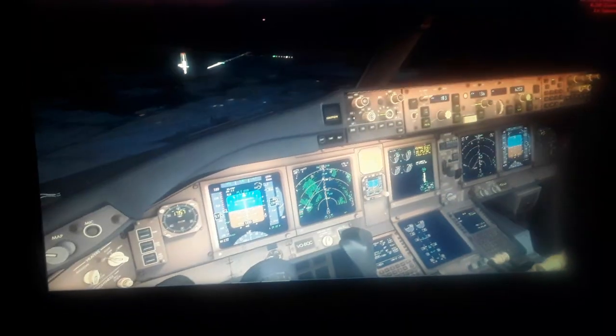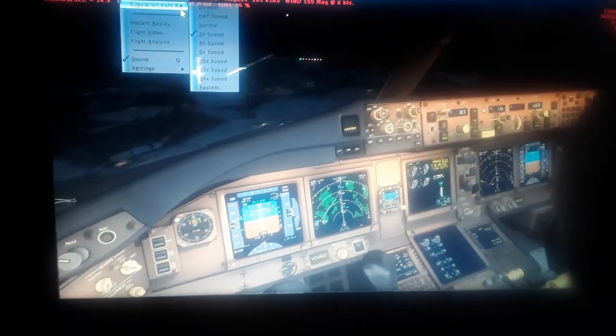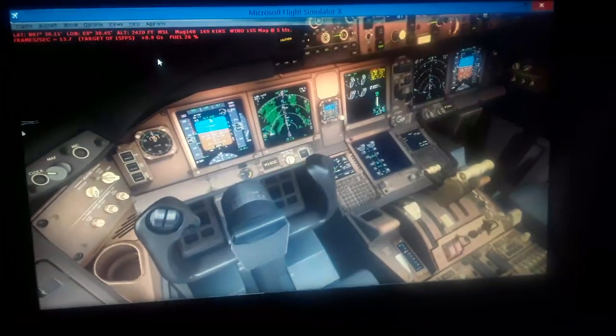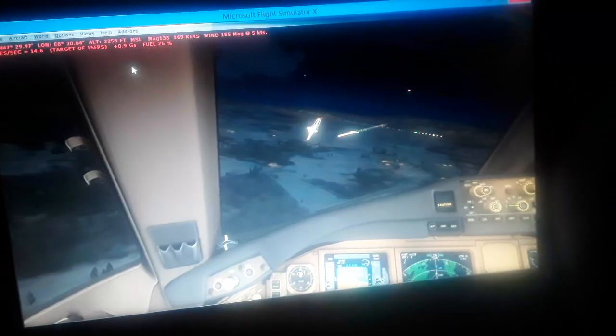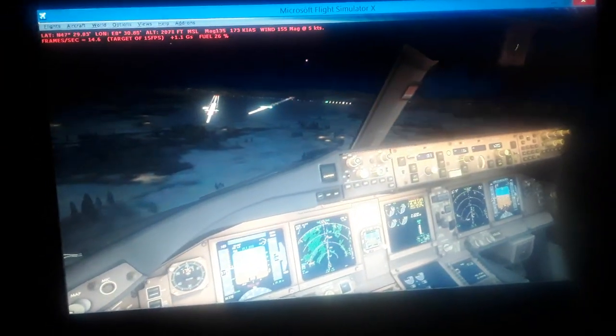You can see the ground below. The airspeed is above the stall speed as it should be. So we use manual glide control, increase the rate of descent, and align with the center line of the runway.